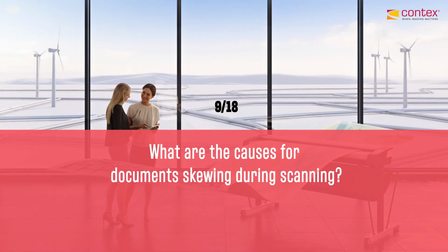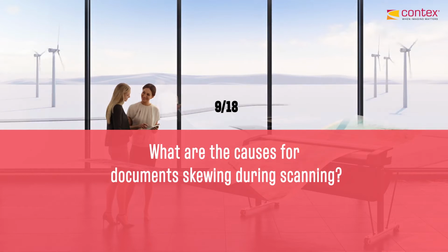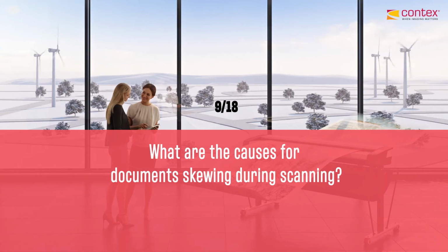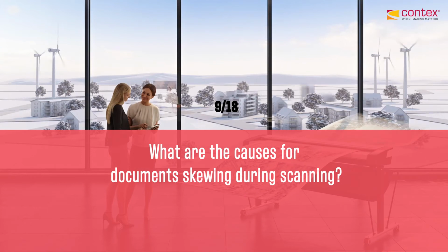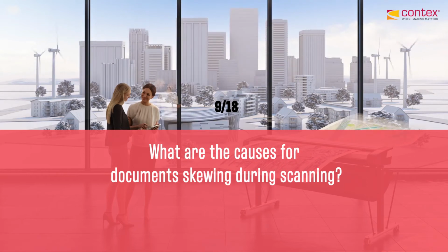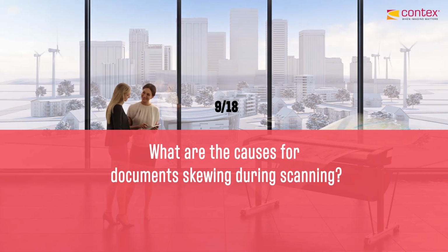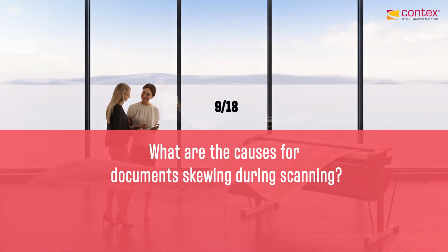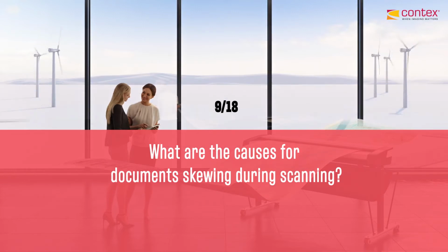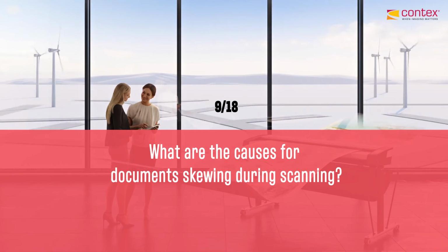So the best thing to do, especially with newer scanners, is just use a lint-free cloth with water, and wet the cloth, then open the lid, use the paper advance button to turn the rollers, and just take your thumb or a finger and clean each roller very quickly, and you'd be amazed at how much of a difference that makes alone. So cleaning the lower feed rollers is your number one thing to check.